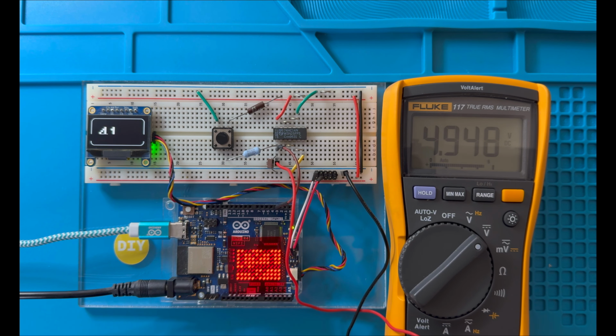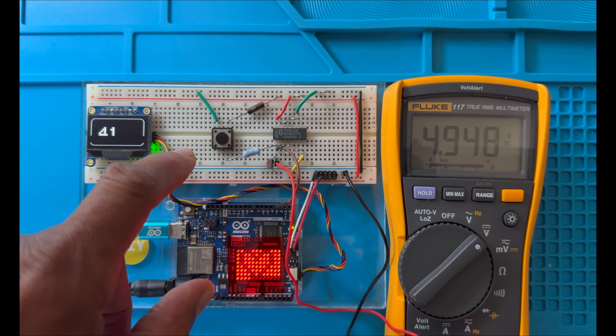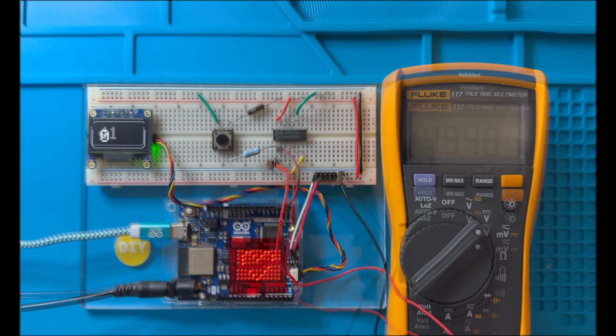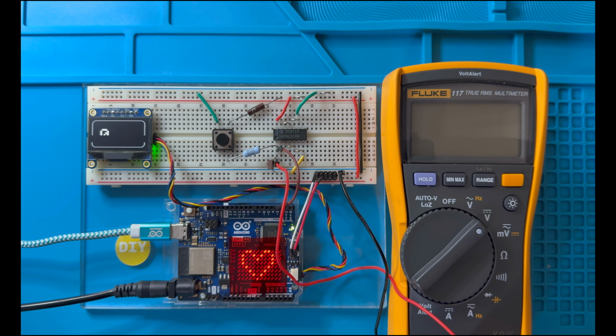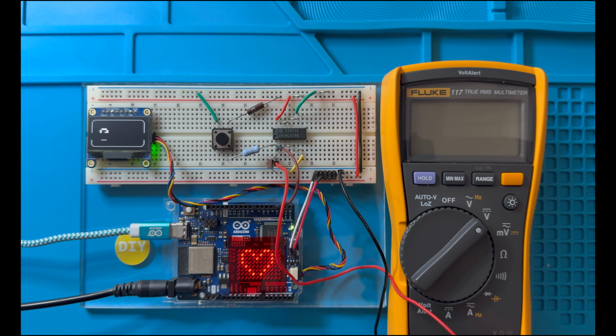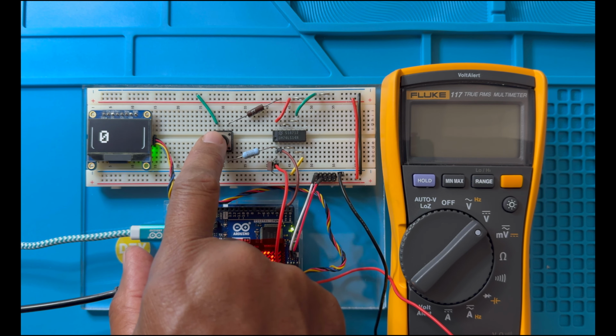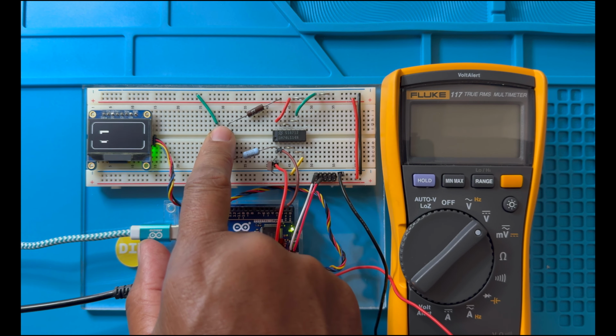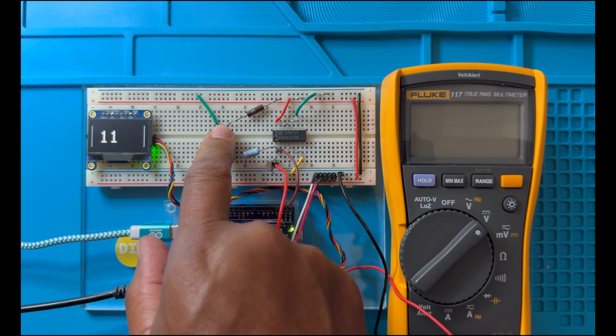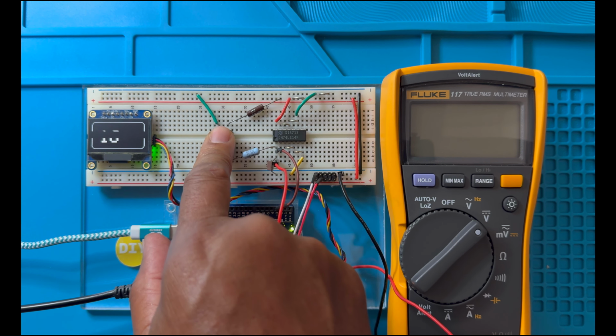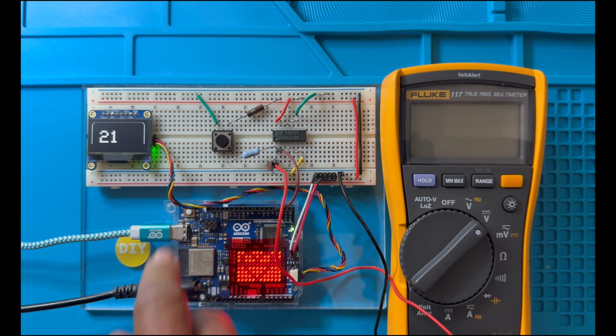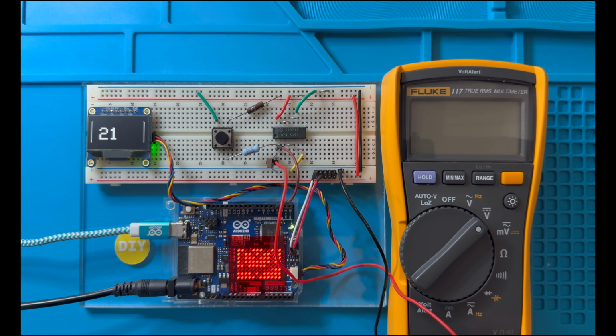So we'll demonstrate that. I'm going to take the 7414 out and put the LS in. Okay, now we have the 74LS14 installed, so let's check that out. 1, 2, 3, 4, 5, 6, 7, 8, 9, 10. 1, 2, 3, 4, 5, 6, 7, 8, 9, 10. Well, it missed one. So let's see why. It's right at the margin.